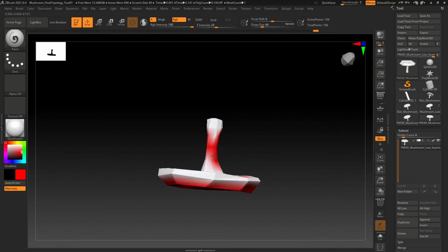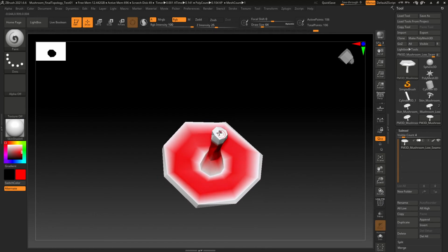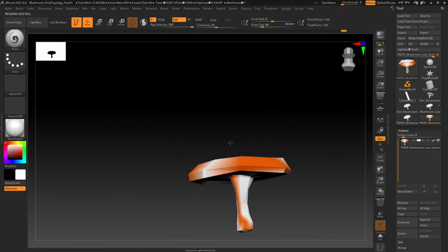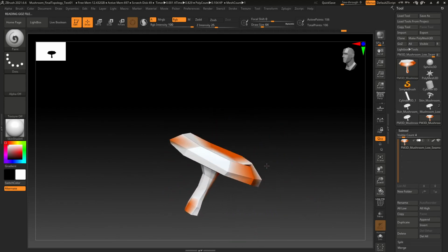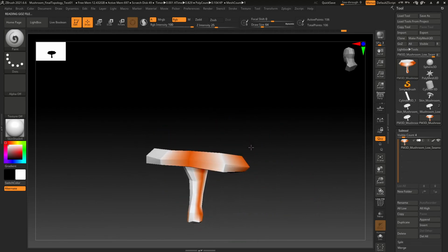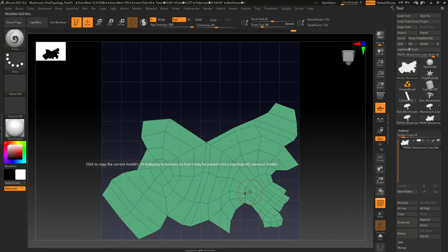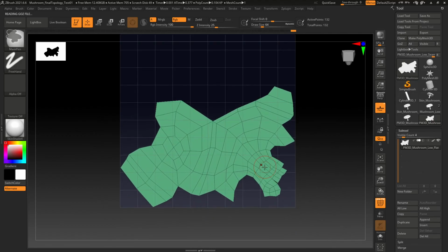But the reality of it is that they're going to have to be somewhere, and I'd want to protect this front face as well. So let's give that a try. Press unwrap, and see then it's moved the seams to a little bit around the edges. Still not quite the level of control that we can get with 3ds Max, but if we go to flatten again, you see that it's done a lot better job than it did the first time, just through doing the protect areas for that.